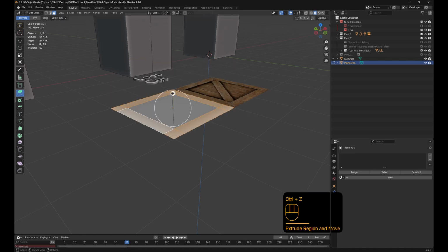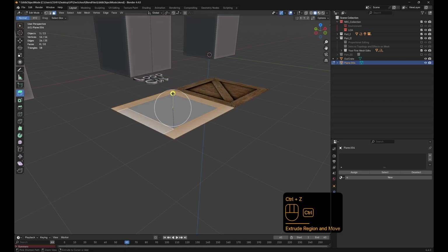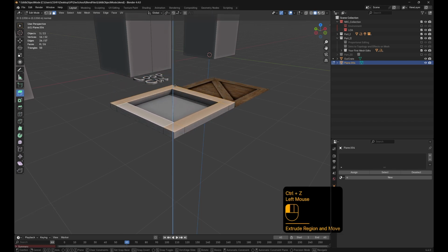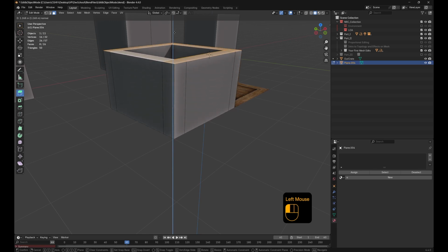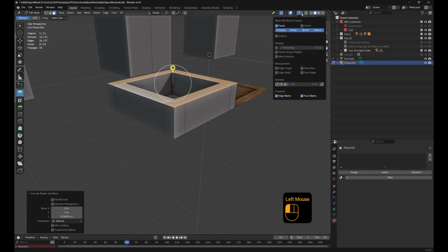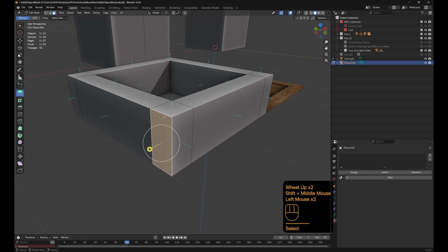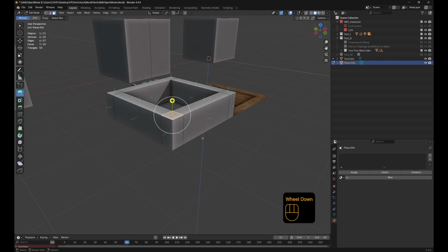Normally when you extrude, you do want to constrain it to an axis, and when you hit that gimbal, that yellow plus sign, what's happening now is, I know it looks like the Z-axis, but it's actually extruding all of these faces along something that's called their normals. If I come up here to Mesh Edit Mode Overlays and come down to Normals and then click this one, okay, these little blue lines, that's a normal. And that's the direction the face should face in a nutshell.